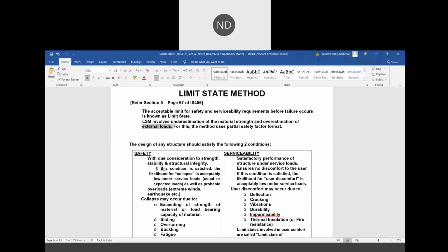So when we design in such a way that we consider the material is weak, obviously we are going to have more safety. We are going to add a factor of safety to that, so that when extra load is applied, or if our material quality is also bad, or we had to compromise in some material quality, your structure is able to resist those kinds of extra loads.